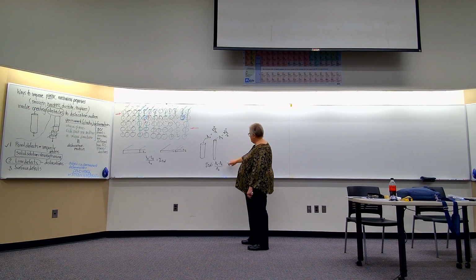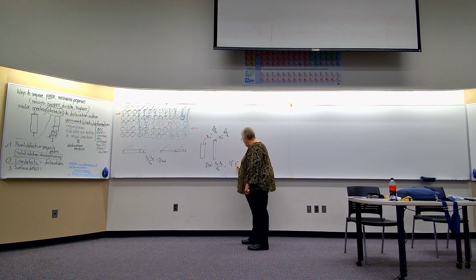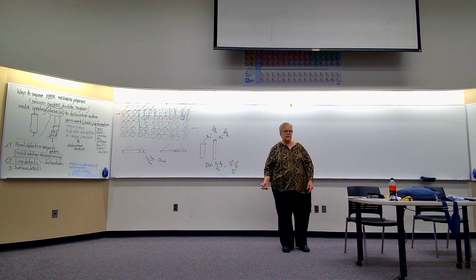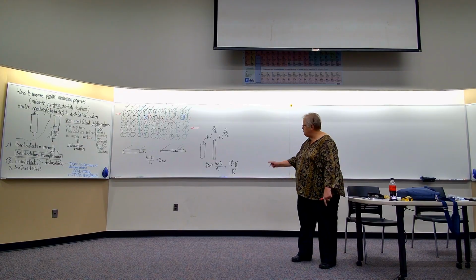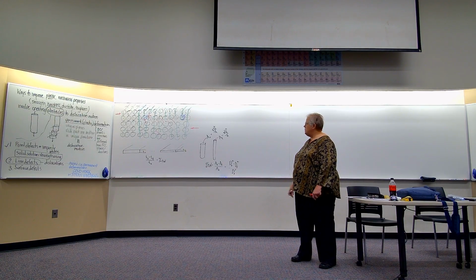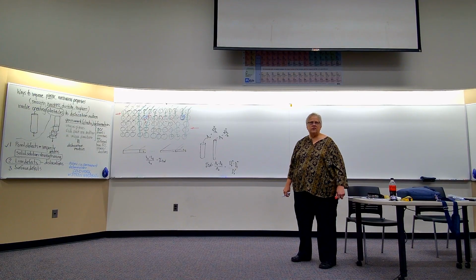So if I put this in terms of the diameter, that would be diameter original squared minus diameter final squared over the diameter original squared. Both cases it's a percentage, but just notice that when I'm doing a circular cross-section, I use area. When I'm doing a flat plate, I use thickness.